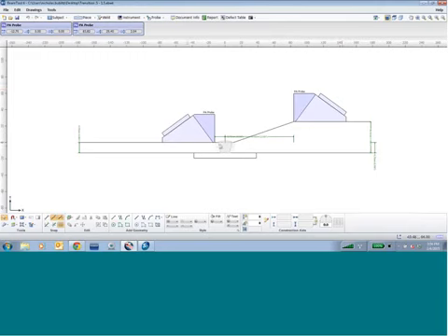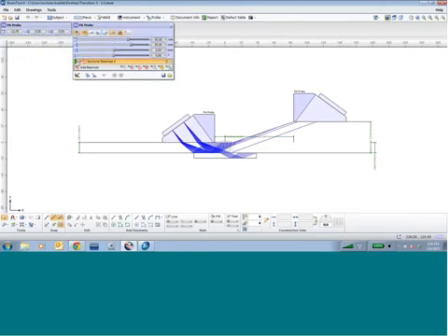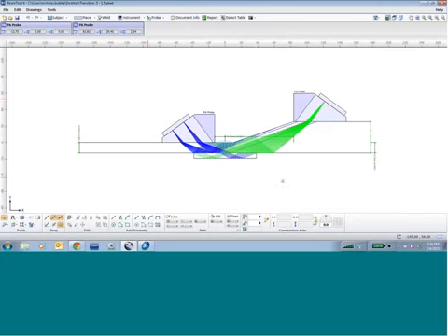So you end up having to do very similar things in changing how you intersect to that area with different sectorial scans, making sure that you really change up the angles that are interrogating those areas. And on this side, from the transition side, you really have to pay attention to what you're using for the elements and how many beams you're dealing with here. Not just the angle, but again, how you get those angles.